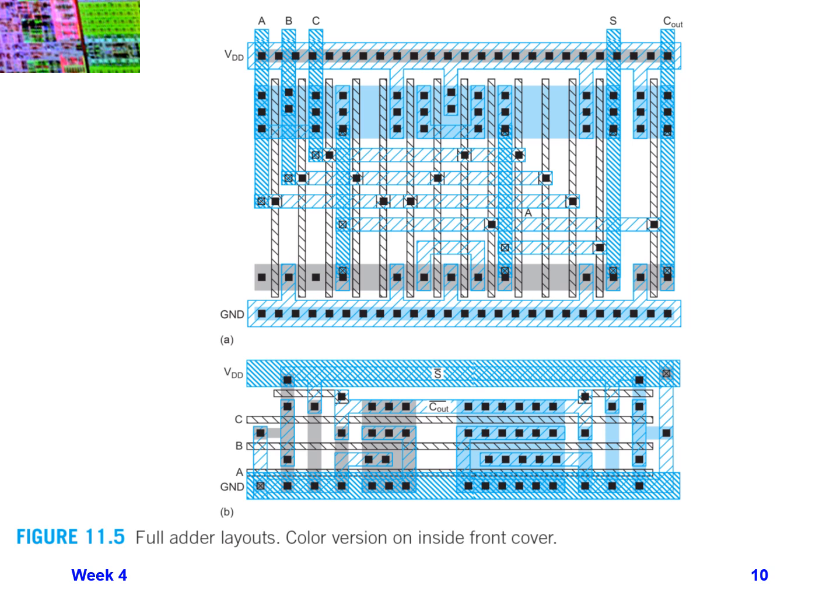Now in practice, as far as I'm aware, most modern process technologies don't allow you to do poly pitch vertical and horizontal, and you don't get to decide. You can only do vertical. So personally, I don't think I would ever wind up doing the one on the bottom.